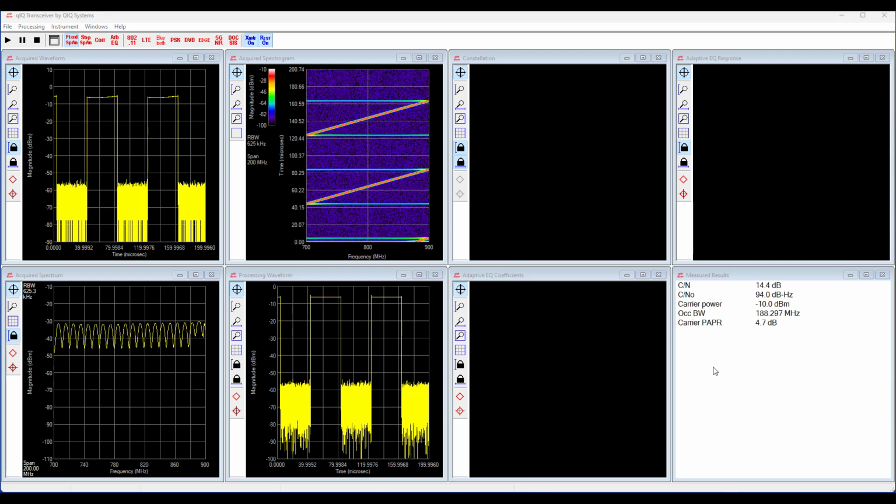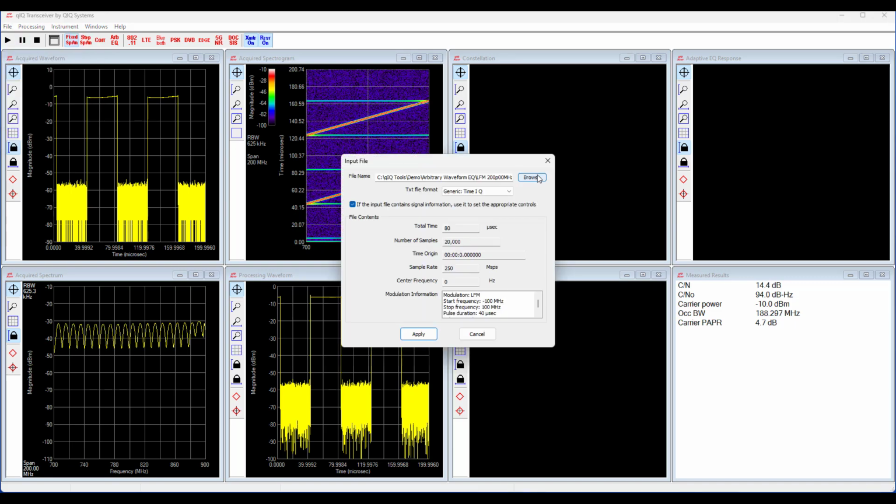So at this point, the idea is that we have created a set of complex FIR tap coefficients using the chirp waveform across the entire usable bandwidth of the signal. Now we want to put that to work for us in doing some usable reduction in EVM. So let's go up here and call in a different kind of transmit file.